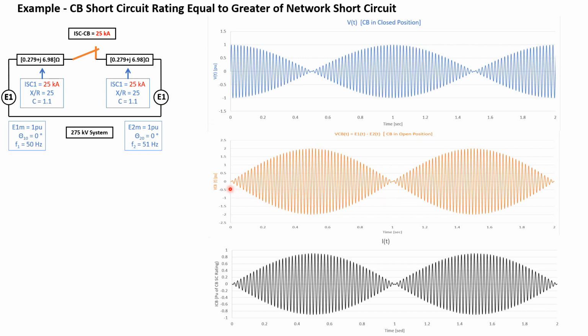So you see that the pattern of that is it's going to reach 2 per unit, and then coming down, and when the RMS voltage of the circuit breaker is almost zero, it is maximum. If we open that at this point, I should expect to have a 2 per unit voltage over the contact.